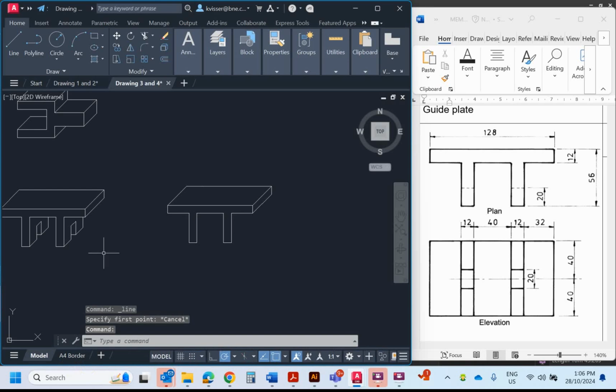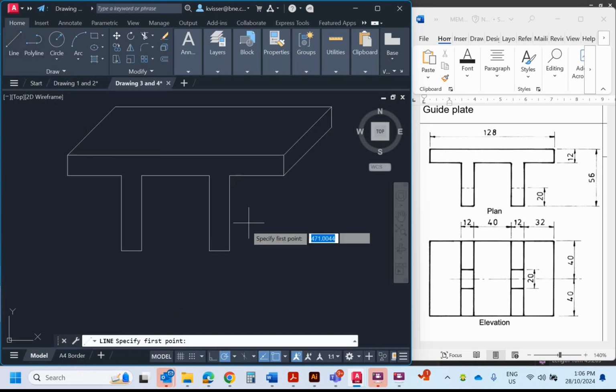Drawings 3 and 4. So projecting back, that's when I'm going to need to divide the distance by 2. So if we take a look at this one here, I want to project back to this point. So I've got 40, and then that's 20 there. So from there to there would only be half of 20, so that's 10 in real life from there to there. And 40, so that would be 30 mil from that point to that point.